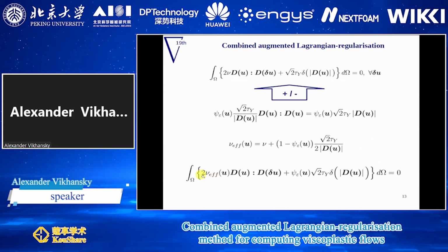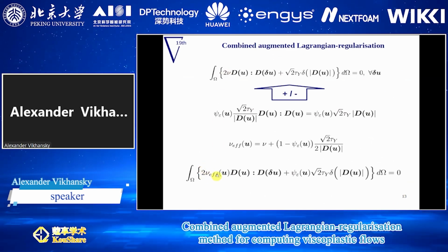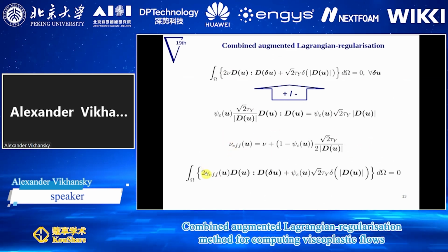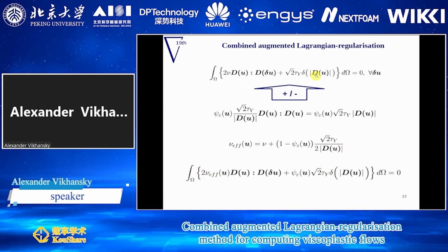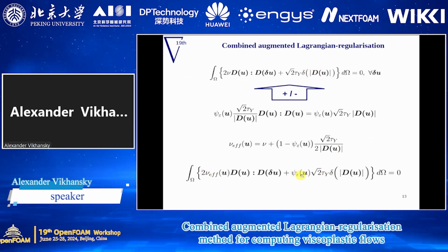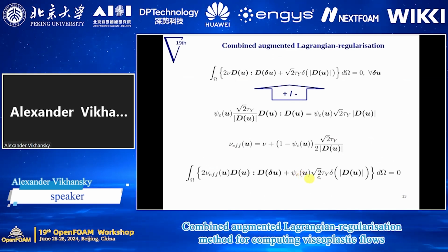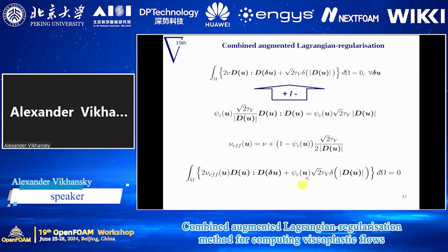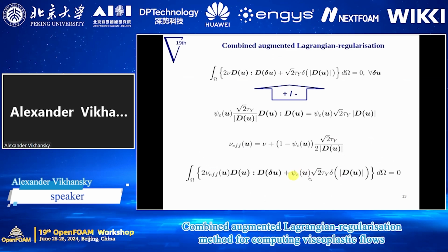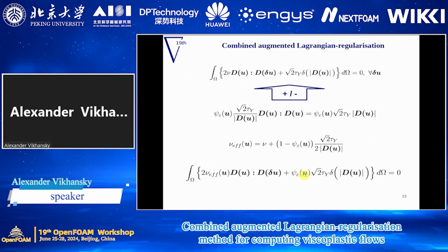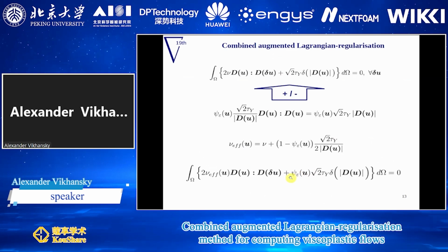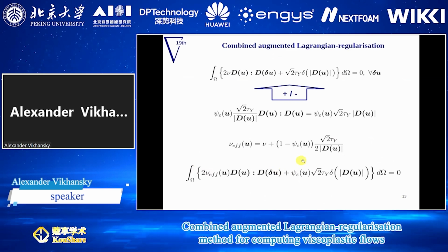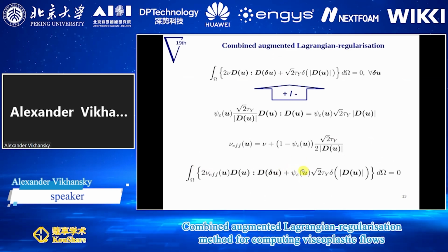If you make the comparison, you can see instead of viscosity, I have the effective viscosity as Papanastasiou prescribed, right? And if I look at the plastic dissipation term, now it's multiplied by the regularization function. It means that this non-differentiable term is active only in a narrow region where the deformation rate is really low. So in the rest of the flow, I use the Papanastasiou model because there it doesn't introduce any error.